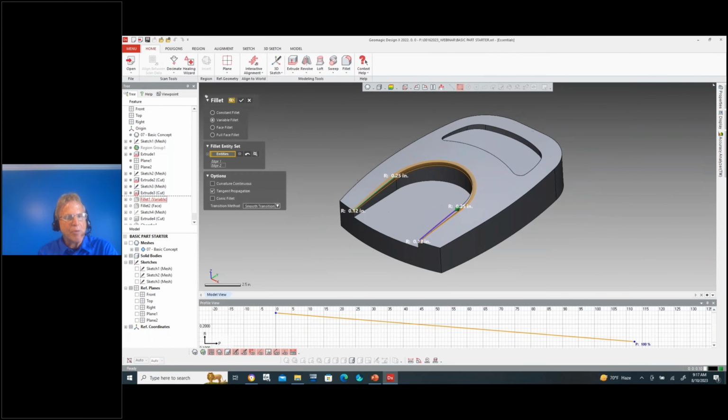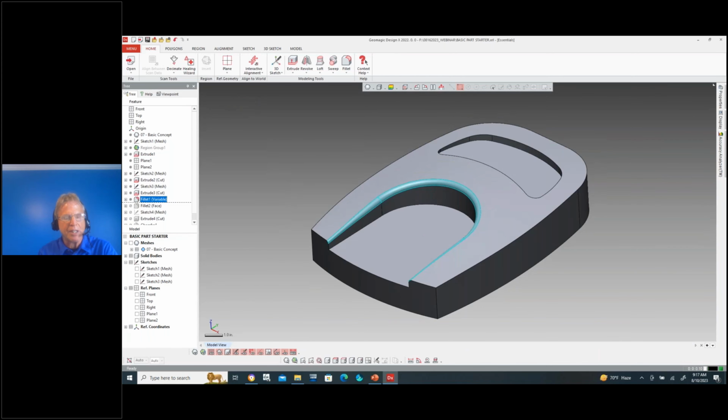Stepping our way through features, DesignX Essentials does have variable fillet radius capabilities. And in this case, the mesh has a fillet that goes from an 1/8 inch up to a 1/4, wraps around the radius of a 1/4, and then reduces back down to an 1/8 inch. So our software is capable of handling variable radius fillets if they exist on the mesh.